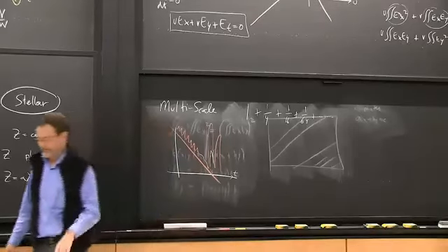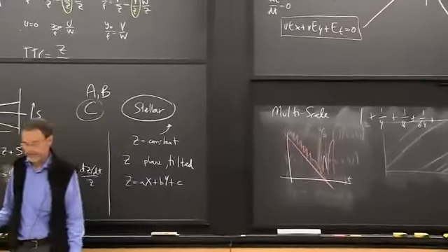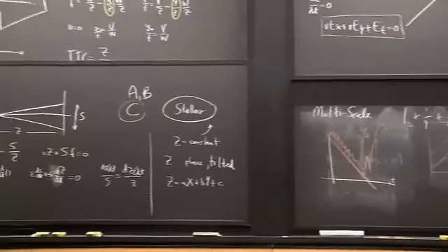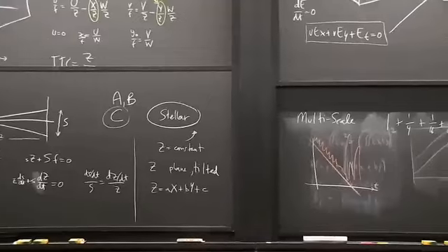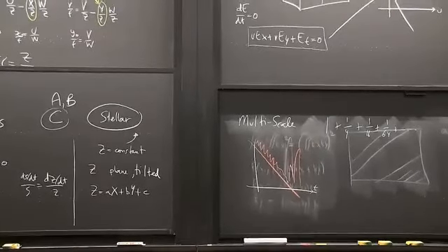And we'll talk a little bit later about how to do this subsampling. Those of you who've taken 6003, of course, realize that you can't sample without getting aliasing unless you've low-pass filtered first. So actually, what you want to do is low-pass filter and then subsample. And you don't necessarily need to subsample on a scale in x by 2 and y by 2.